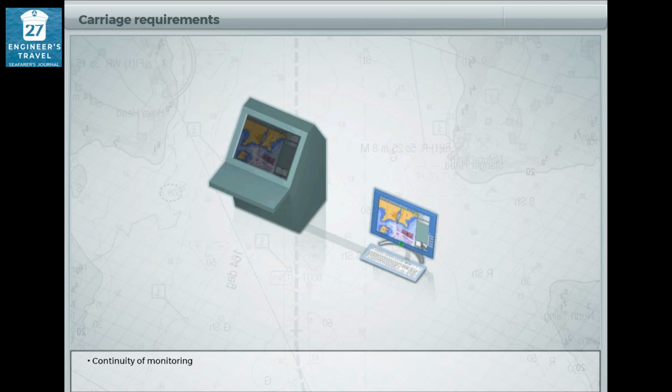If the ECDIS fails, IMO require the backup to be instantly available to ensure that failure does not result in a critical situation. The backup should provide for safe navigation for the remaining part of the voyage. It should be capable of geographic representation, with route monitoring and voyage data recording as the main ECDIS would.